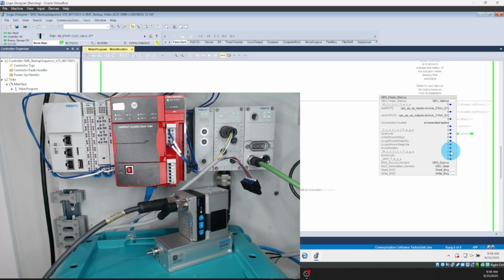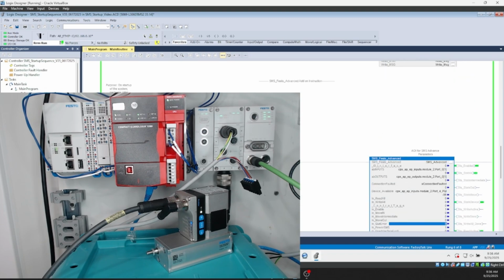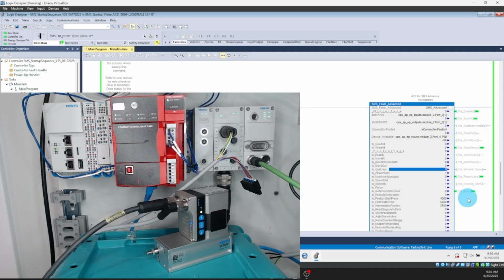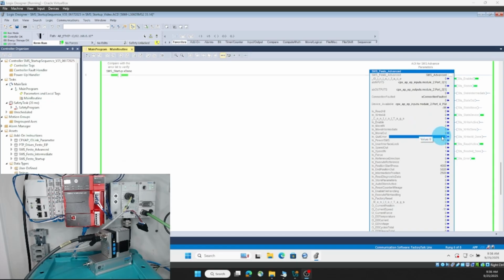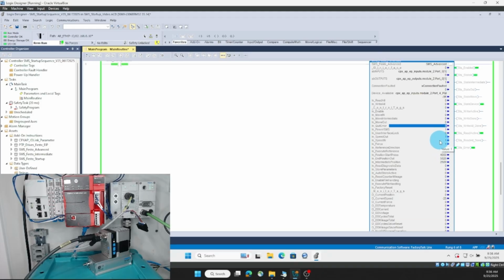Now when I go back online, I'm going to see that the start is done, and now you can see, let's switch this back. Now that I have a done status here, I'm allowed to use the original AOI, where I can now tell this to move out after first recovering from an error, which is from the original communication loss.